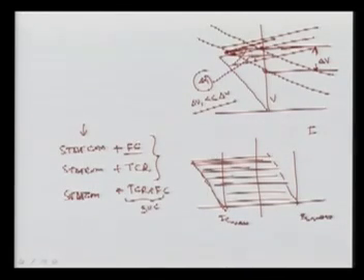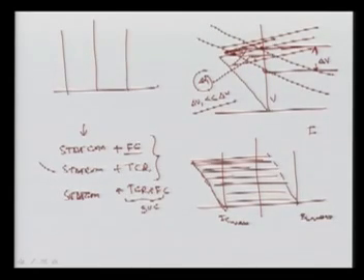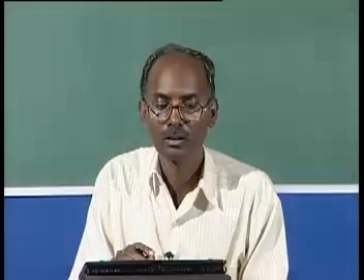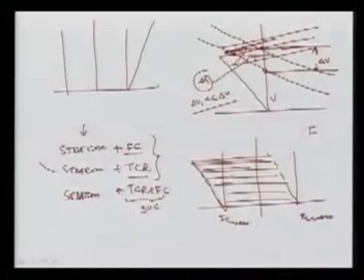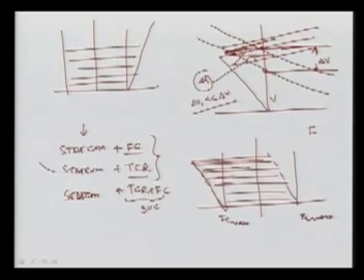Now if you have the STATCOM plus TCR, the characteristic is again like this. The TCR is nothing but this characteristic. It is the variable one, so we can go from 0 to here, and we are adding only this region, so we get this characteristic completely. Or we can add the STATCOM and SVC, and that will serve the purpose over the whole wide range in that area.